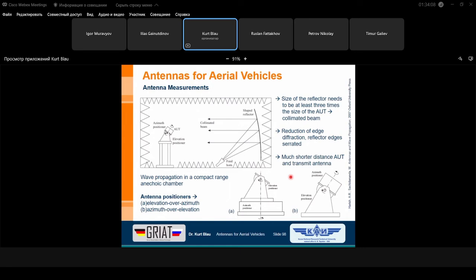And then you can say, okay, the bandwidth is, let's say, 20 megahertz. The center frequency is, for instance, 20 megahertz minus 10 megahertz. And then you can tell him, to the left and to the right of the center frequency, please measure the pattern in steps of, let's say, 5 megahertz. Then you have at least the pattern in steps of 5 degrees at, for instance, 5 different frequencies.